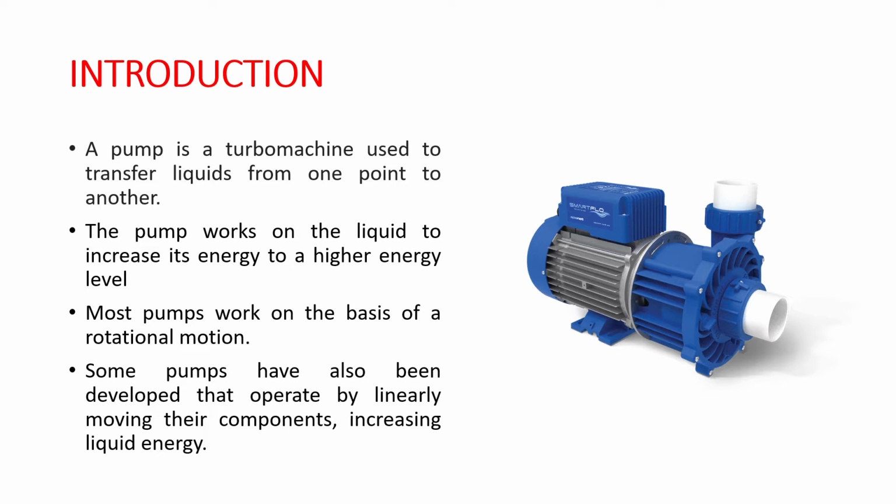A pump is a turbo machine used to transfer liquids from one point to another. For this purpose, pumps use mechanical energy. The pump works on the liquid to increase its energy to a higher energy level and consequently its pressure. Most pumps work on the basis of a rotational motion. However, some pumps have also been developed that operate by linearly moving their components, increasing liquid energy. The source of energy for pumps is usually a fuel engine or an electrical motor.